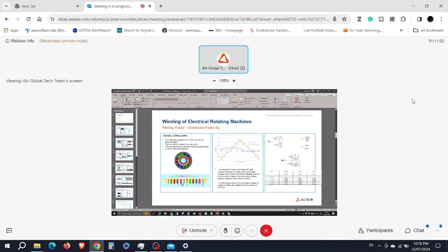What we are going to do is measure the voltage. So we are going to move the rotor at a given speed, and then recover the voltage for each coil, and recover the voltage of the full phase with all the coils in series. One can think that the total voltage we are going to recover is simply a multiplication of the voltage of each coil, and actually it's not the case.